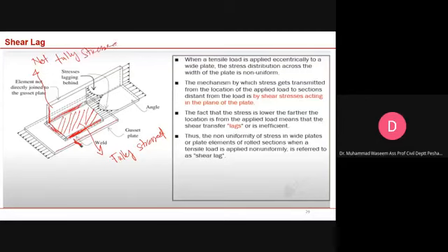So there will be a lag of stress transfer. You can see the stress distribution in this member; the stresses will be lagging. Once you have this type of scenario, we call this situation shear lag.